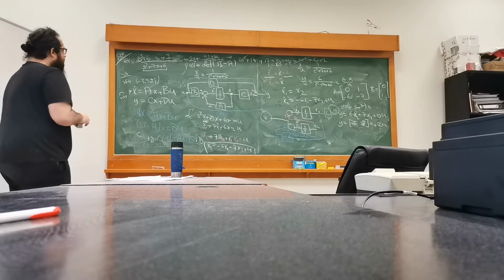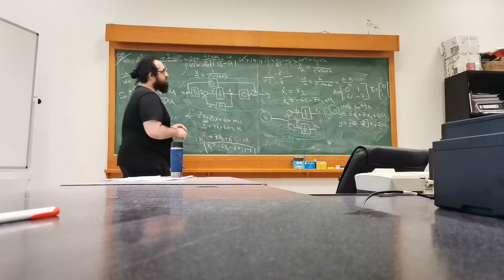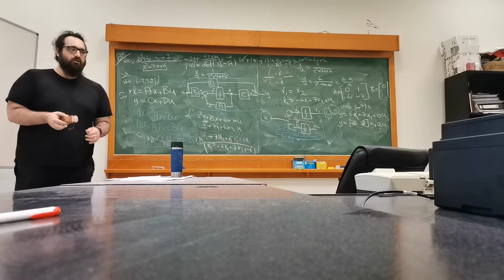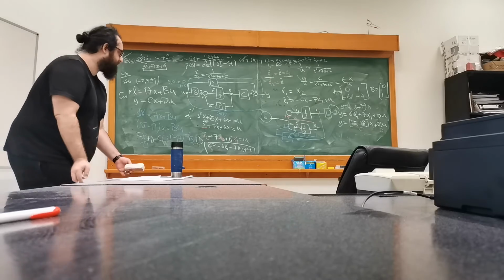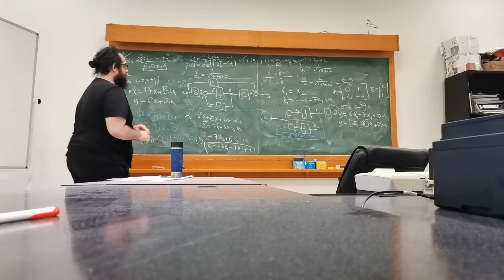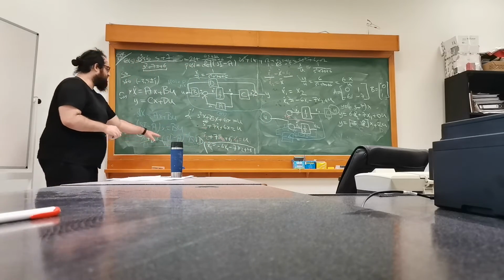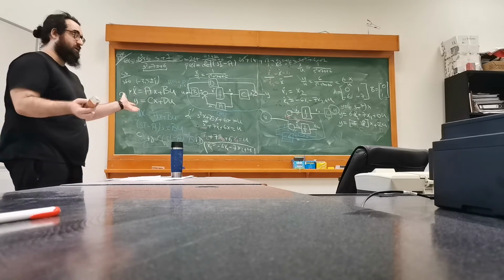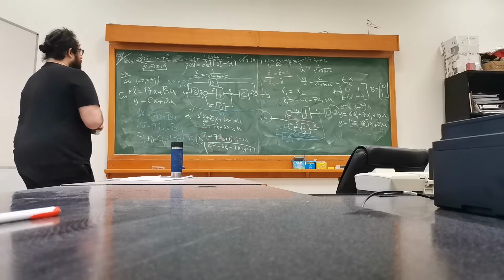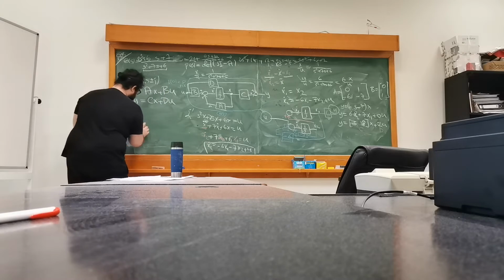So once you are done with the conversion from transfer function to state space, what you can do is take A, B, C, and D and plug them into this and see if it's working or not. Of course, this would be time consuming for an exam, so it's way better to just be careful with these steps and be sure that it is correct. Otherwise, you have to take the inverse of a 2x2 matrix if it's a 2x2 system, and that would be time consuming. So now, let me write down the actual A and B matrices here.